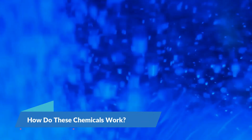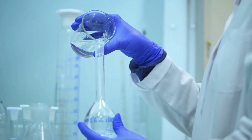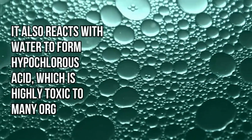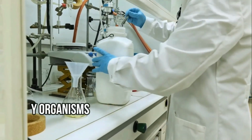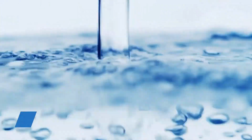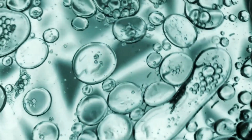How do these chemicals work? Mechanisms of action. Chlorine. Chlorine kills organisms by breaking down cell membranes and disrupting processes inside the cells. It also reacts with water to form hypochlorous acid, which is highly toxic to many organisms. Iodine. Similar to chlorine, iodine penetrates the cell walls of microbes and disrupts their internal structures, rendering them inactive. Chloramine. By combining the effects of chlorine and ammonia, chloramine provides a more stable and longer-lasting disinfection process, which is less reactive with organic compounds in water.